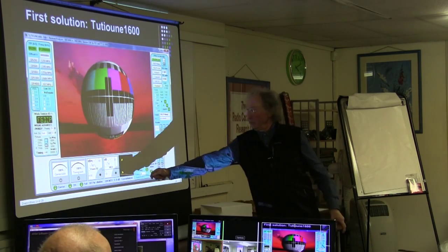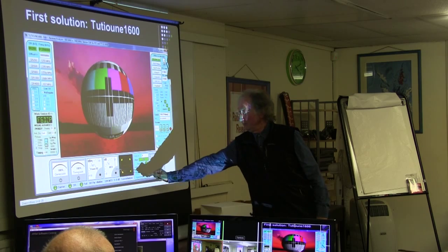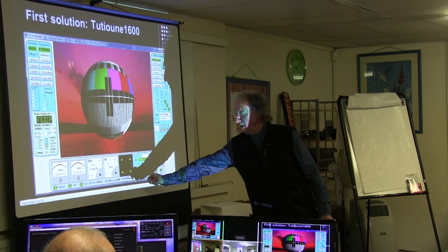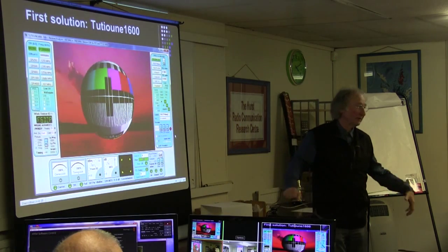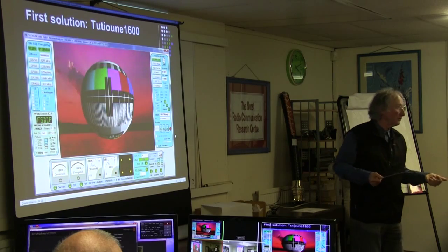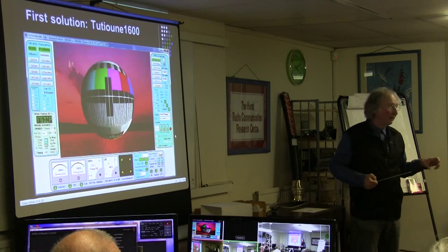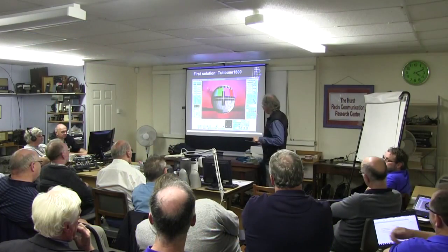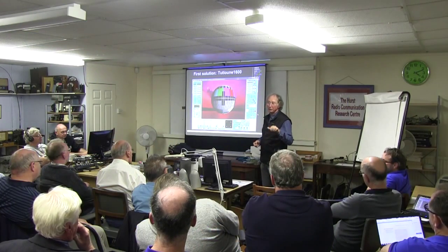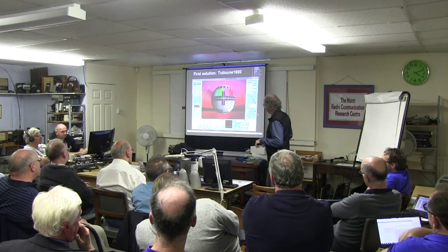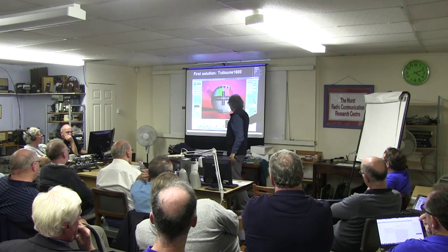So we can measure the RF level, the MER, that is the best value for us for a report. It is the signal to noise, the digital signal to noise result. And we have the constellation.